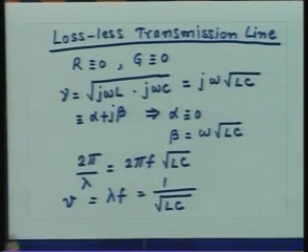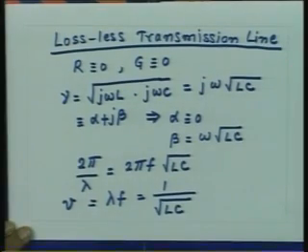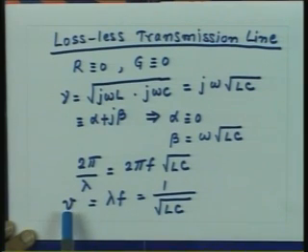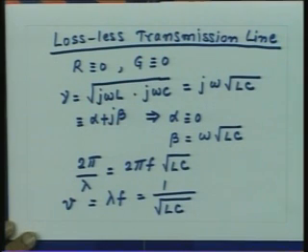In fact, the problem is not that. The situation is exactly opposite. The velocity is a parameter which is decided by the field distributions and the boundary conditions, as we will see a little later in this course. That means the inductance and capacitance of a transmission line are not independent, because this quantity V is decided by some other boundary conditions on the transmission line. So, once the velocity of the travelling wave is fixed by some other conditions, the product of L and C is constant, and this one can see physically.